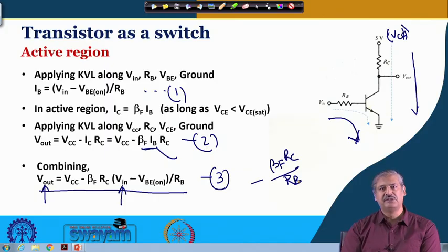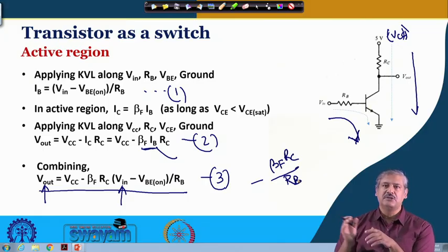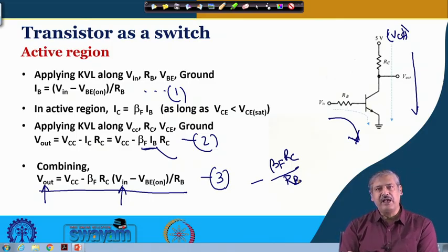So, if we want a faster fall, since often the circuit remains in one of the two stable switch states, logic 0 or logic high, we would like to have this transition region, this active region, which is also known as transition region, with width as small as possible.